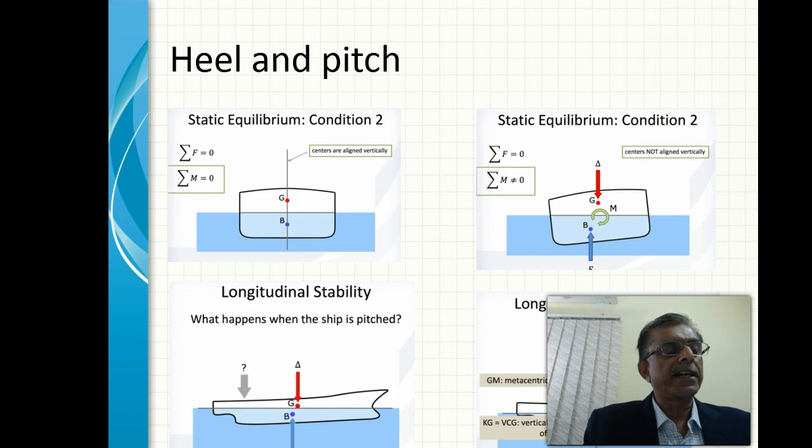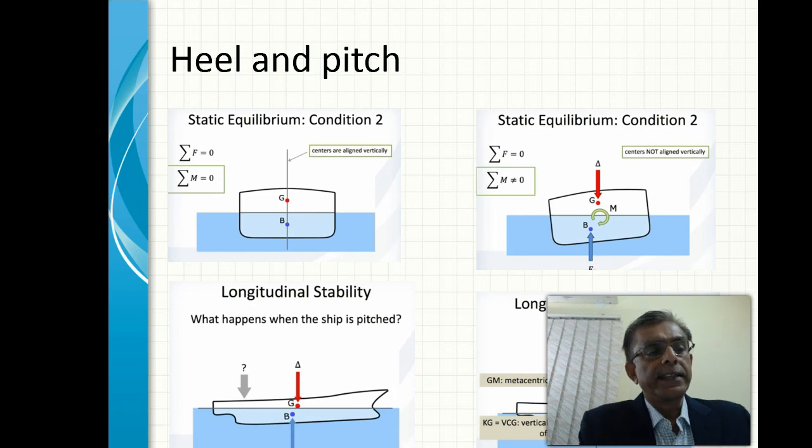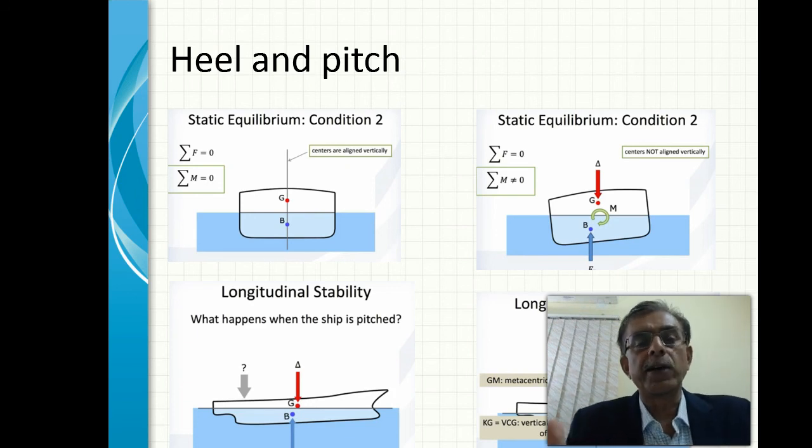So the vessel starts getting pitched and trimmed based on the positioning of the center of gravity and the center of buoyancy. These are aspects which the ship's master is very much in control of because these are dynamic processes. But during a design phase, a naval architect will look at all the varying possibilities and ensure that the metacentric height, etc., meet the various design requirements.